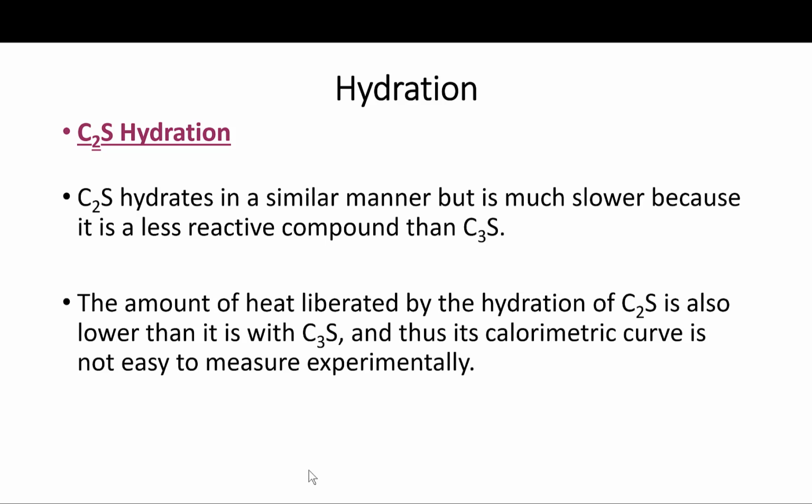Okay, so let's look at the hydration of the C2S, the dicalcium silicate. C2S hydrates in a similar manner, but much slower because it is a less reactive compound than C3S. The amount of heat liberated by the C2S is also lower than it is with C3S, and so its calorimetric curve is not easy to measure experimentally. So you need to remember that.